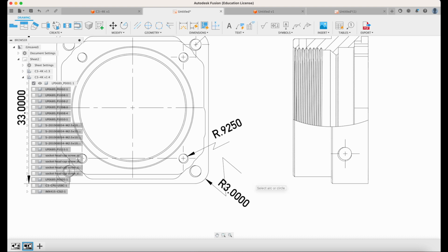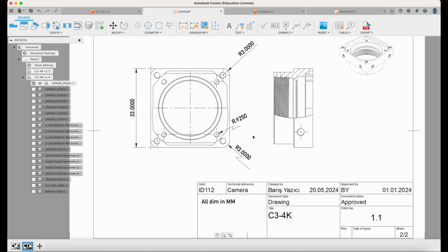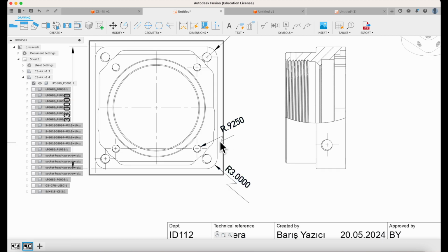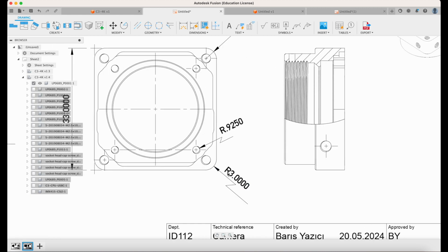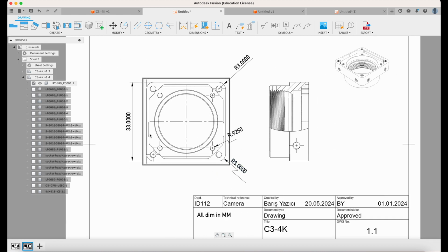Click escape, click on the line, and do something like that. So this jagged line, the jogged line as Fusion calls it, is much harder to mix up with what's in your drawing, so people don't get confused about the lines for the dimensions and the actual drawing.